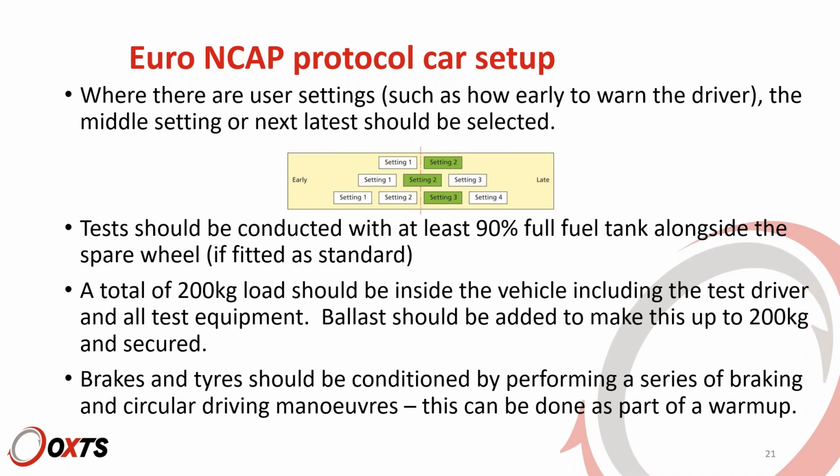And lastly, the Euro NCAP specify that a series of braking and acceleration maneuvers, so circular driving and figure of eights and that sort of thing, should be used to condition the tires and the brakes. This is because most of the time these tests will be conducted with new tires, new brakes, and that shouldn't bias the results. But whilst the warm-up of the RT is obviously an important step that takes a little bit of time, because it's a requirement that the brakes and tires also be conditioned by Euro NCAP, this maneuver itself can actually function very well as a warm-up.